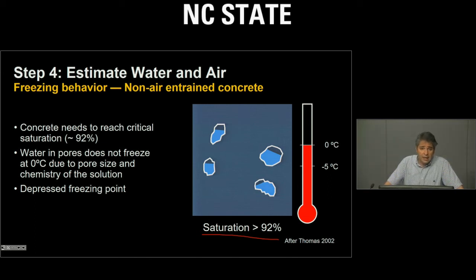Now, however, in concrete material, we need the concrete to be at a degree of saturation of around 92%, and I will tell you that 92% is not an exactly correct number. It turns out that it is something around 88%. However, the idea is that if we don't have a lot of water inside the concrete, we don't worry about freeze and thaw. If the concrete is completely dry, no ice will form in it, and therefore there is no freeze and thaw durability issue. But if concrete has enough water in it, let's say around 92% for simplicity in this particular case, and ice starts to form, ice will start to expand.